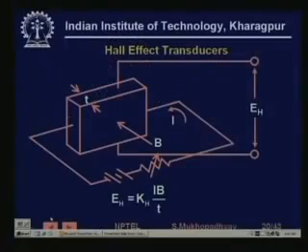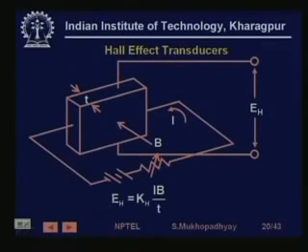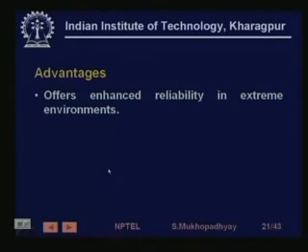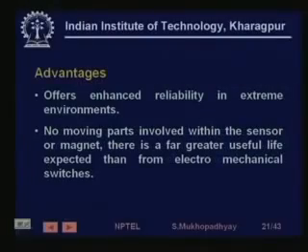Similarly, Hall effect sensors are used for various reasons. One of the main reasons is that it is very reliable. There is no contact required, it is a non-contact environment, and there is no moving part in the sensor. If you embed it once in the stator, it is going to work.